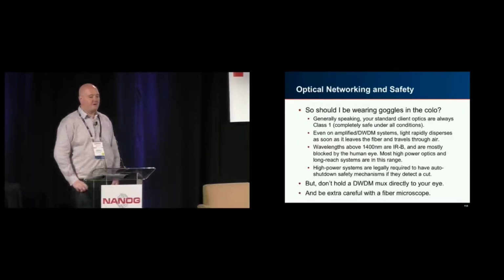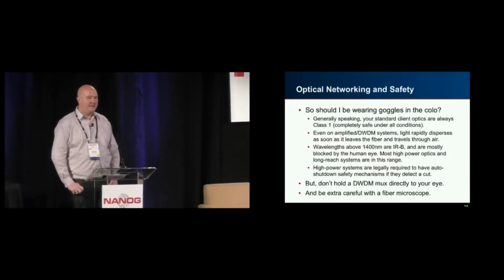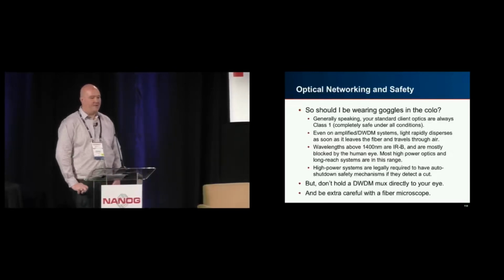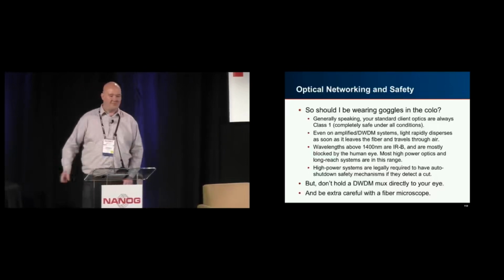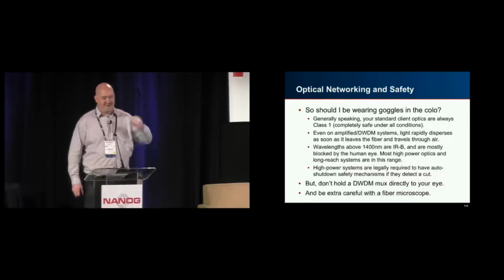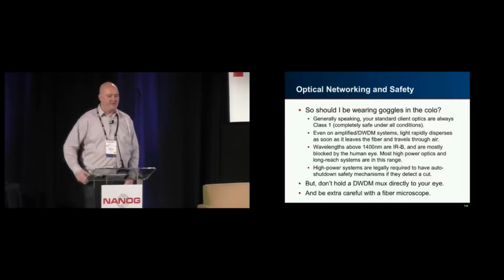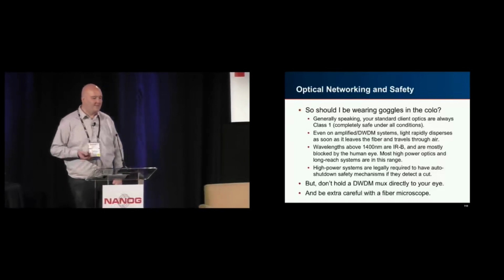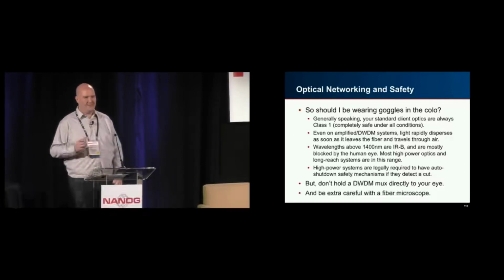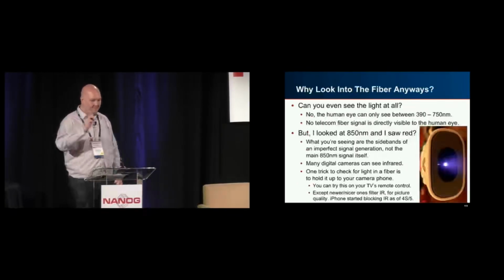So should I be wearing goggles to the colo? Probably not. If you're playing with your standard client optics, you're in no danger whatsoever. Even on your amplified WDM systems, the light really disperses quickly once it's inside air. So unless you take the fiber and hold it right up to your eye, you're probably fine. And remember that everything above 1400 nanometers is actually mostly blocked by the human eye. So don't worry about it too much, but don't look at it with a microscope either. So why would you even look into the fiber anyways, right?